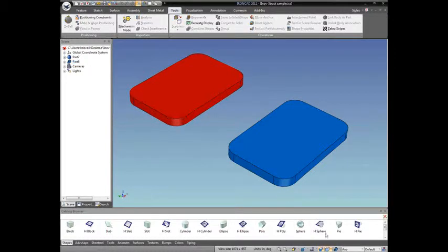And how you determine what is being created: if you look down here on the icon, there's a little pop-up menu. You've got structured and you've got innovative. Whatever is selected at the time that you create the part, whether it be drag and drop or through extrude or whatever, that's what mode the part's going to be in. Once the part's in that mode, it's stuck in that mode. You can't go back and forth. So that's something to keep in mind.